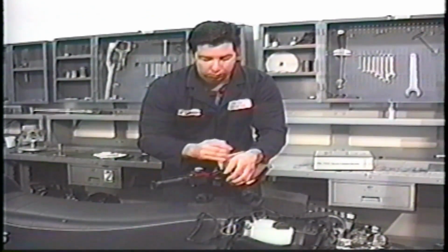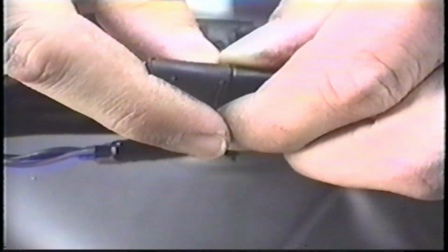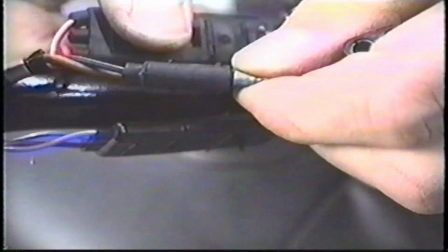The next step is to eliminate the control switches. Disconnect the black wire coming from the CDI box, or on snowmobiles, you can disconnect the CDI wire at the kill switches. A partially shorted kill switch may cause an intermittent spark problem at operating engine speeds.